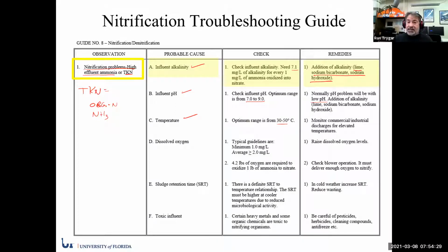In some plants in the United States, we may not see it get that high, even in the highest temperature ranges in the summertime. So a temperature somewhere between 20 to 30 degrees Celsius is more normal in some areas, but as the temperature gets closer to 20 degrees C, we're going to start to see a definite slowdown of the bacteria not performing as fast.